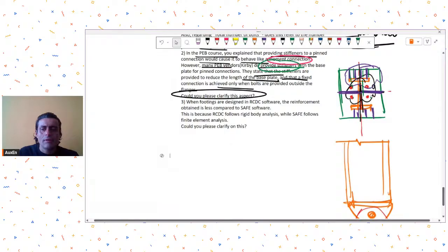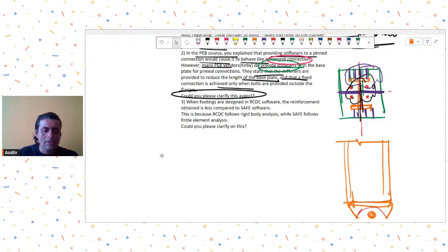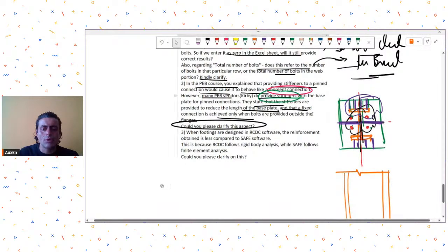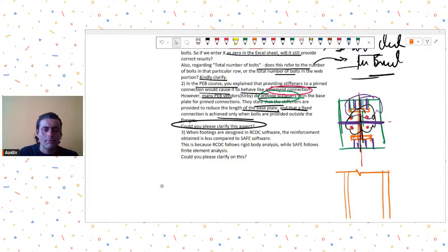Okay. But yeah, tension element is the bolts, and as long as tension bolts are close to the centroidal axis, there will be no tension taking elements. So providing stiffeners may not make such a large difference in the overall moment resistance, but I would like to have no stiffeners connected to my column and base plate in a pin connection.